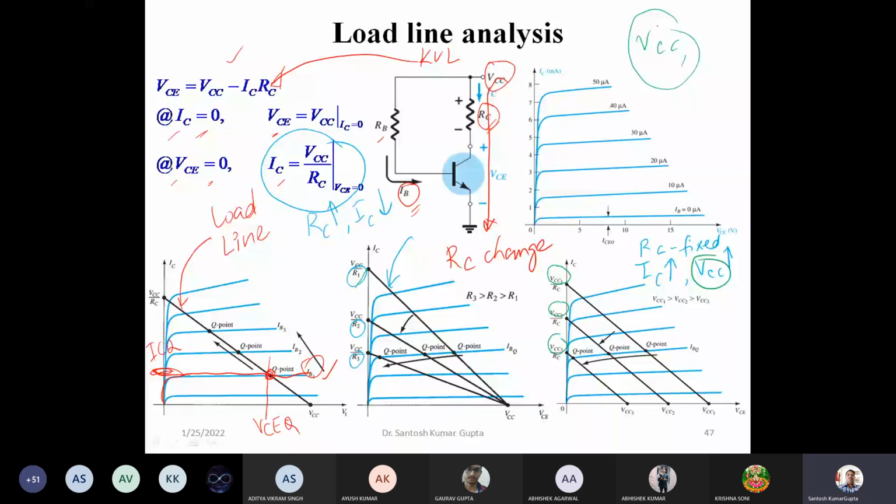That is the operating point. Another type of question could be that it may be desired to have a particular value of IC, and the transistor may be given to us, and we have to design. Design means we may have to find out the RB, RC, and VCC values, or even the VCC may be given and one may have to find out the RB and RC. So those kinds of problems could be there.